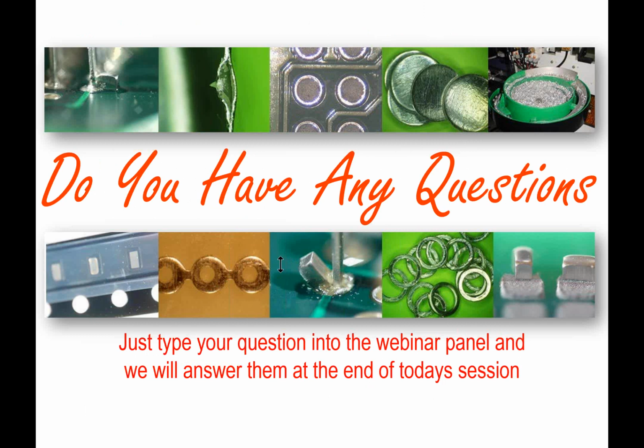Hi, yeah, in this case, if you're interfacing a preform into a solder joint, I would always recommend sticking with the same alloy, because then you don't have any other intermetallic phases or any interactions that could change the melting temperature or the mechanical property of the solder. So yeah, long answer, but short answer is yes, stick with the same alloy.